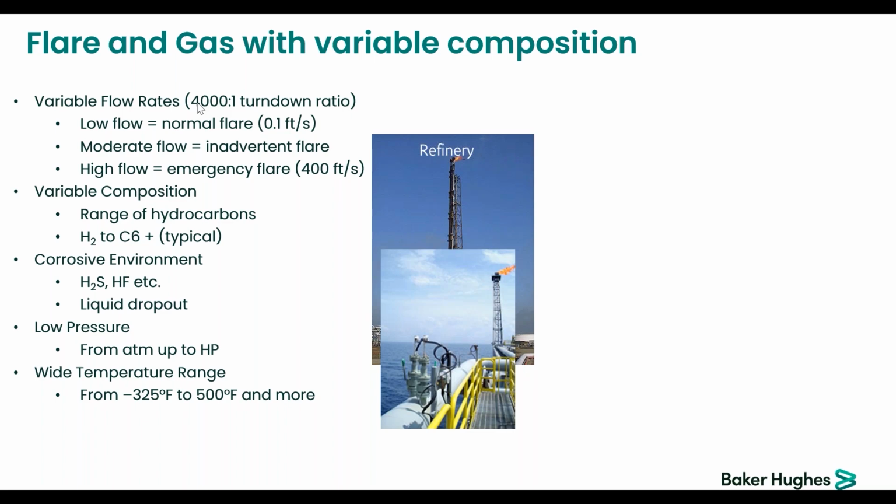And we also have large variations of hydrocarbon mixtures. If I remember the previous question, where my gas temperature varies by 40 Fahrenheit, in this case it varies about 200 Fahrenheit, and the gas composition varies from hydrogen, with a very low molar weight, up to ethylene, for instance, with a very high molar weight. So that makes the measurement very difficult. The window in this case is way larger, but that's at the expense of the accuracy.